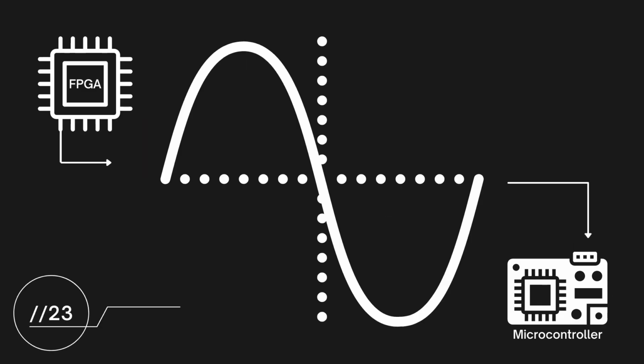Knowing that the continuous signal emitted from the FPGA is sampled at a set frequency and stored as an ordered list of values, we're able to reconstruct a digital replica of the waveform. And by taking the absolute difference of each sequentially sampled pair, we are able to determine whether a signal is changing and by what quantity. Further, by summing these differentials, we are able to determine which circuit from a given population has the maximum change in its output signal. So this is what we'll evolve for, circuits that produce larger amplitude signals than their previous generation.